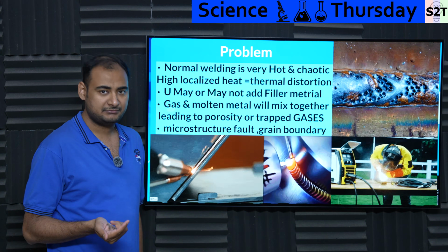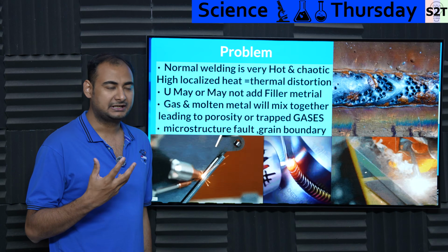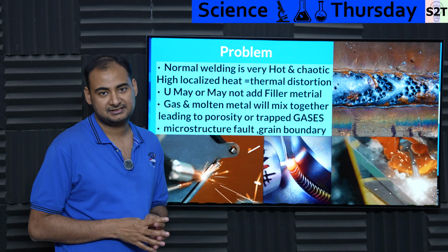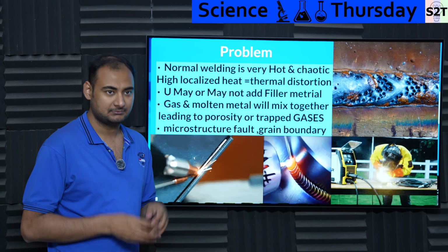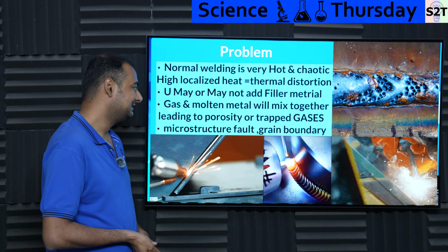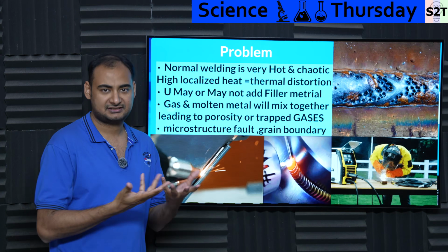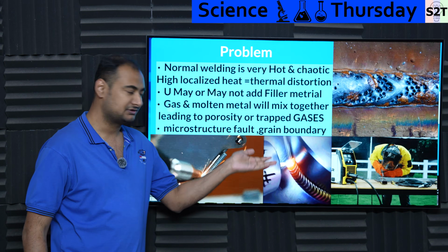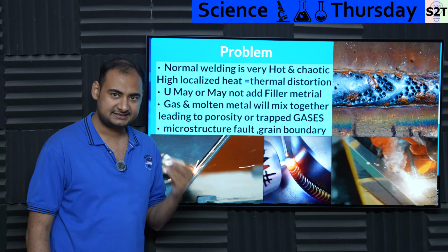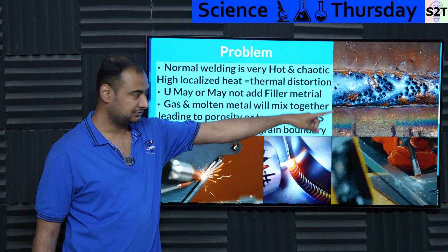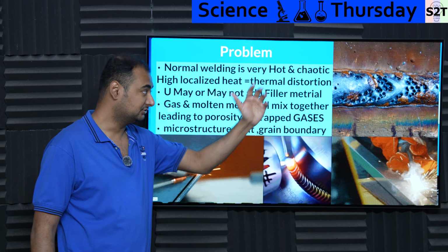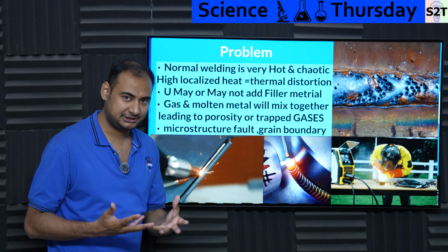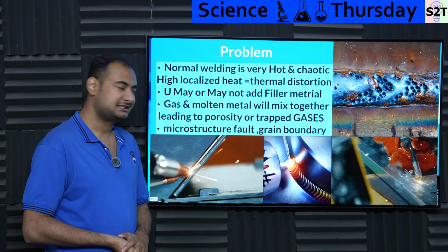And gas and molten metals do not remain inert. A metal could be like, I do not react to oxygen. Here it is, put it to 700 degrees Celsius or 900 or 1000 degrees Celsius, basically liquid metal, yeah, it will react with oxygen. And you're like, okay, what if I have flux gas like that stick? Stick is literally that flux provider, and TIG and MIG also have their own shielding gas. They are still gas, they are still reacting, meaning they could create trapped bubbles, porosity, those sorts of things become a serious issue that you have to deal with. This is by nature. So that's a big issue.